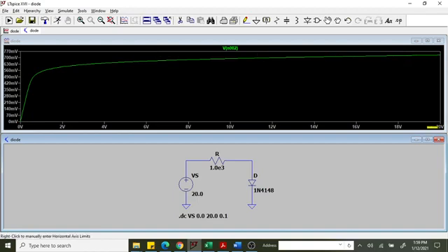And you can see even here when our source voltage is all the way up at 20 volts, the voltage across the diode is pretty constant, around 0.65 to 0.7 volts. But what we want to look at here is this designation for this node here. So this is V(node 2). And so that node to ground is what we want on this horizontal axis.